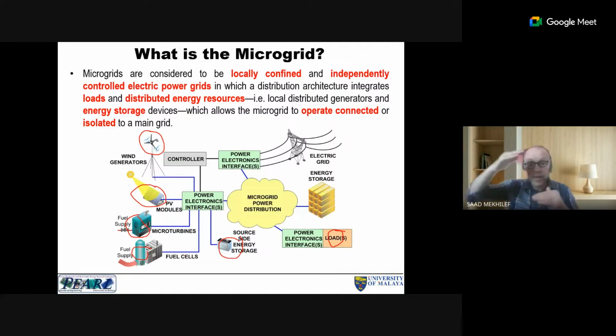This is very important. For example, I want to install a solar power plant, solar photovoltaics. So what is the solar access? How many kilowatt hours per square meter? What are the directions? What is the best tilt angle? This I would call site assessment and technical assessment, which gives you an idea of what would be the optimum design, because we cannot over design, we cannot also under design, so it should be optimum.